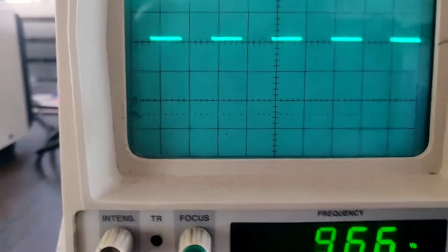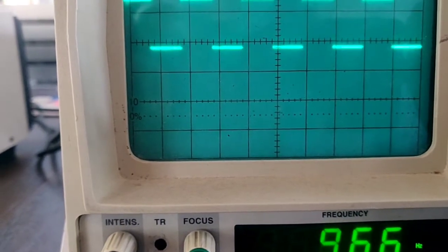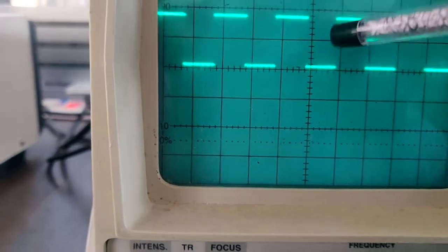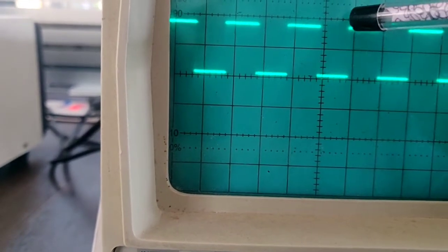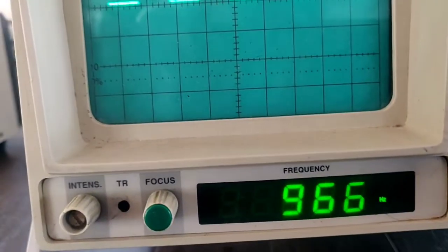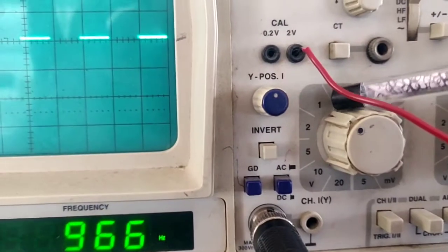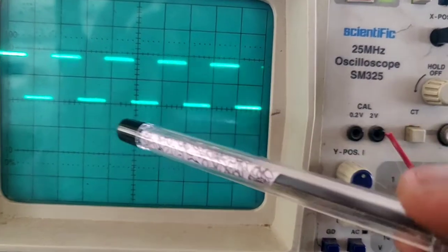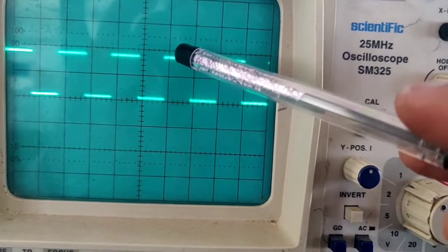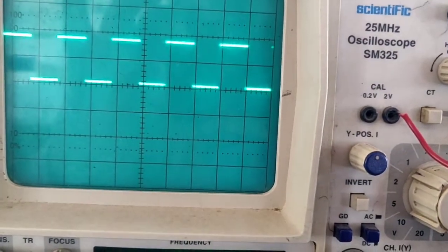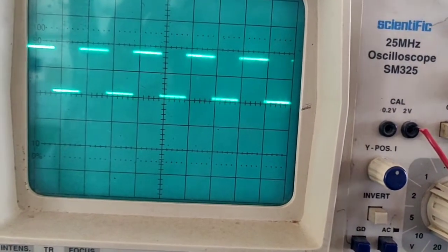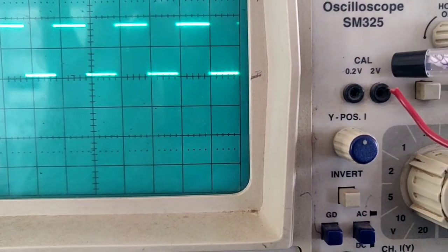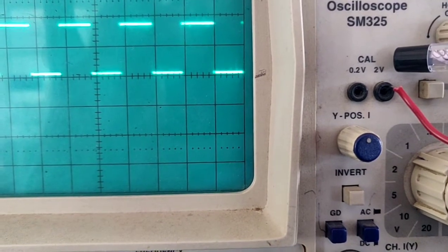See that, adjust this Y position, position on the Y axis somewhere here, and see that there are actually 2 divisions available here. So 2 into, here the scale we selected is 1 volt. So the amplitude is calculated as the number of divisions on the Y axis, here it is 2, and the scale we selected is 1, so 2 into 1, 2 volts. So according to calibration it is 2 volts. That means our CRO probe is in working condition.